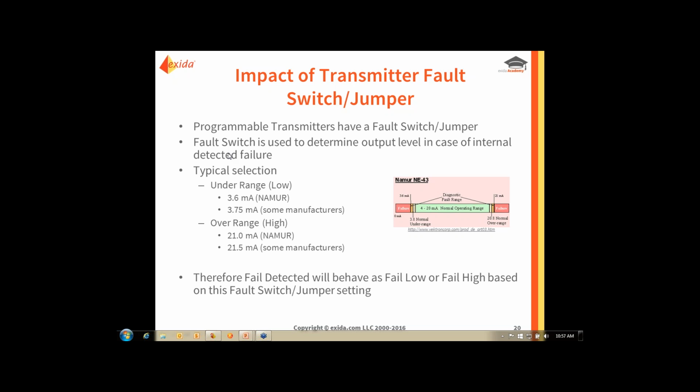Noisy, typically, if you look at the safety manual of a certified pressure transmitter or whatever transmitter, temperature transmitter, level, you will see a safety accuracy. And what that basically says is that within, and that could be 2%, for example, that within 2%, the output is basically guaranteed. So that means that if, for whatever reason, maybe the filter fails, and your output deviates by 1%, we don't really consider that a failure from a functional safety perspective.